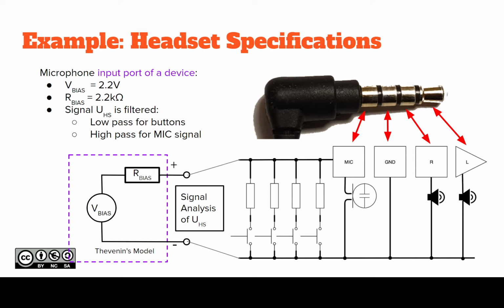No, I don't. Okay, that might be the cancel call or the yes, cancel call. Yes, that must be it. So there we have the buttons and microphone signal on one single analog signal line, and the signal analysis actually takes care that all of those signals are filtered properly and the functions are done accordingly.